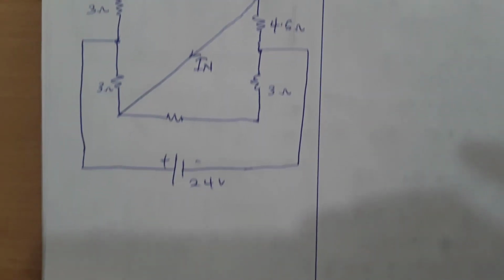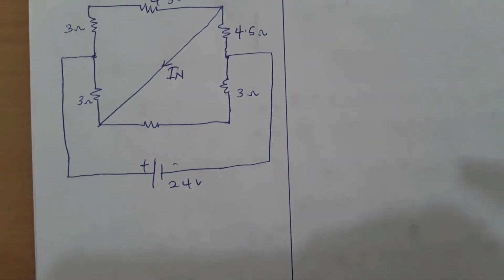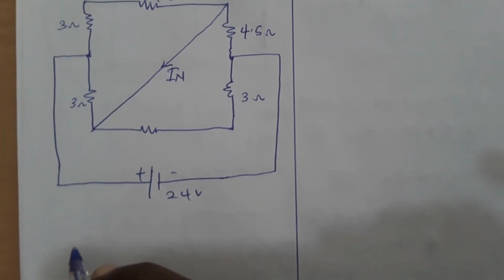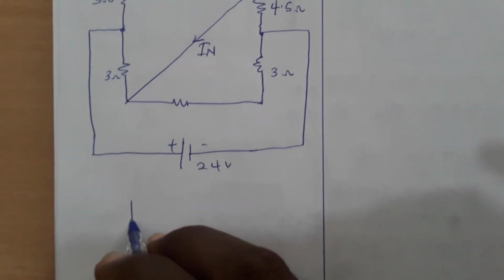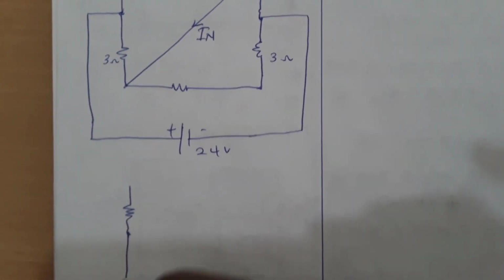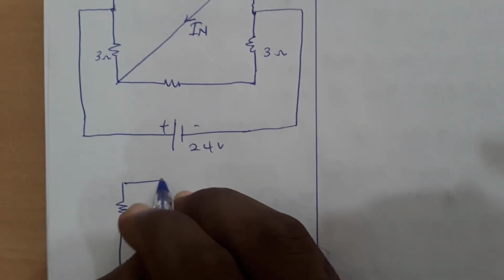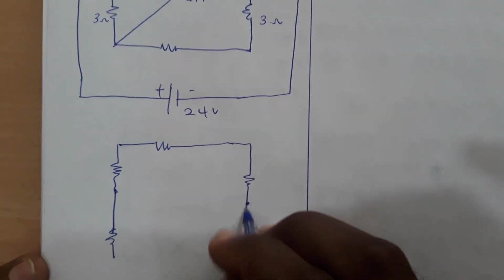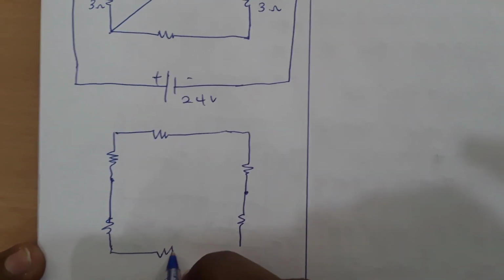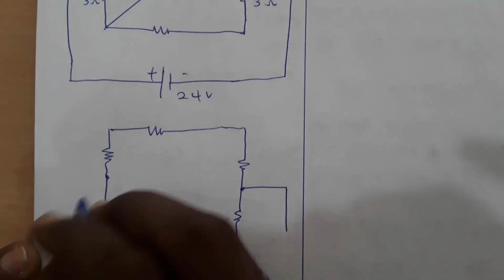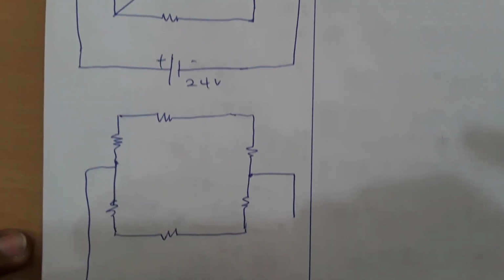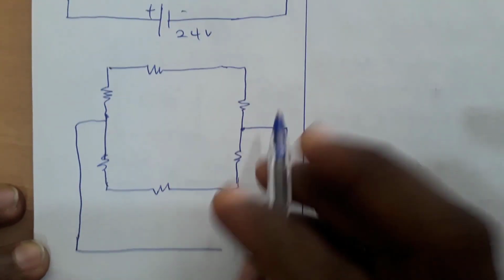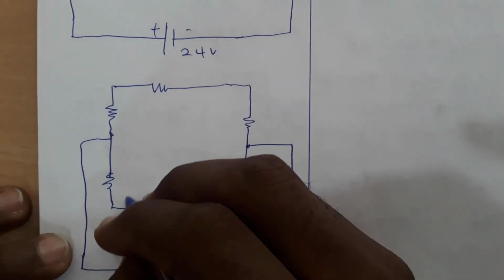So with this question, we will find our RTH first, Rn, because this is Norton. So we'll find our Rn first. Alright, so this is how it will look. This will be the 6. And in finding Rn, we short this voltage source. So it will look like this.